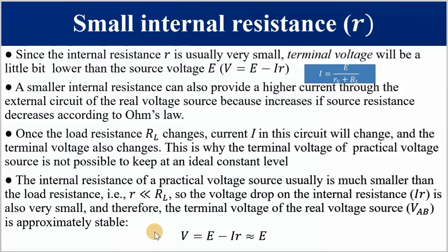In practice, please take note, the internal resistance r is far, far less than the load resistance RL. Otherwise, all our voltage would drop across the internal resistance, and very little would be left to power our load. Our aim is for all the EMF to power our load satisfactorily.